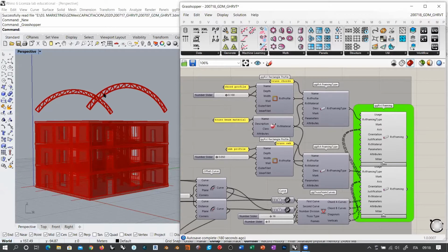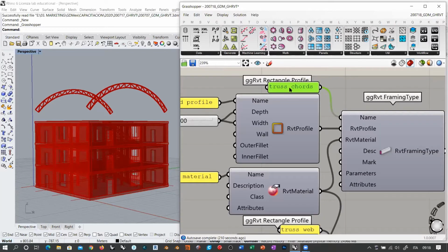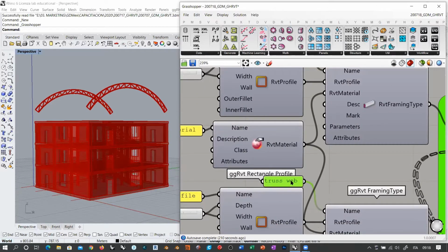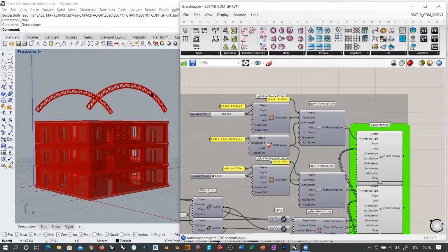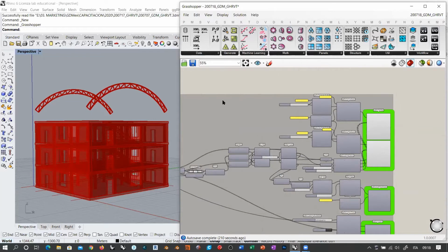So the reason why we want to send this to Revit is eventually to have a parametric workflow here in Grasshopper where we can change things on the fly. And then by simply updating the geometry in Revit, that happens because of the object ID that we were discussing yesterday, we can change, for example, this change that we do here in Grasshopper. It's, well, more or less in real time reflected inside a dimensional scheduled quantity inside Revit architecture. So you know, for example, what would be the final cost for these truss systems, okay, in no time. So that's the interesting thing for us.